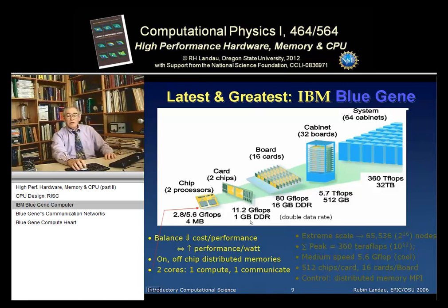And it also has a gigabyte, which is a lot of memory to have just on the card, of DDR. DDR is just memory, and it stands for double data rate memory. And what it means is it's not only the amount of memory, but it's fast memory. It's very fast because you can transfer data on each clock cycle, both as it's beginning the clock cycle and as it's ending the clock cycle. So sort of double speed memory on the card.